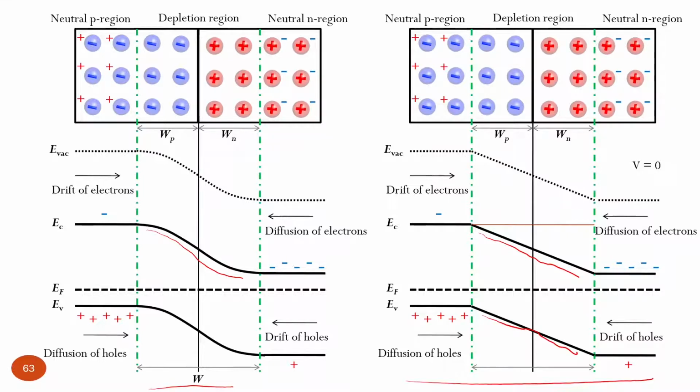However, if our electric field inside the semiconductor material is uniform, is constant, it means we don't have space charges inside the junction. That's this intrinsic semiconductor case, where we don't have depletion and we don't have space charges. Then the electric field is uniform. If we integrate in order to get the distribution of electrostatic potential, we end up with a linear distribution of electrostatic potential. And that's the one here.